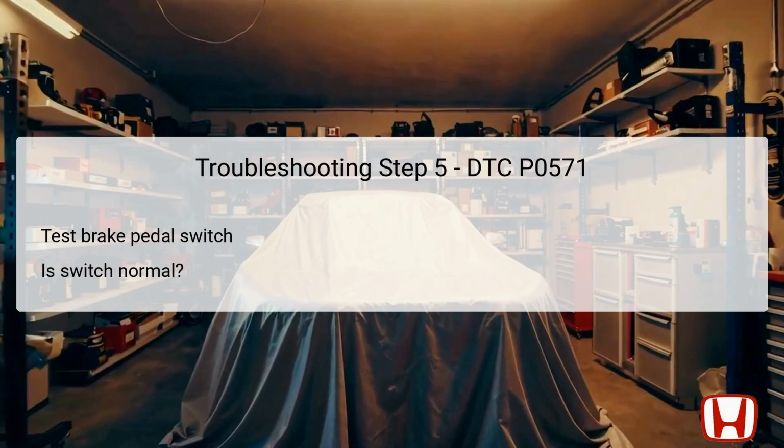Ensuring the switch meets operational specifications allows other diagnostic efforts to refocus on separate wiring or connection issues if the switch checks out fine. In this sixth step, fuse A910A, located in the underhood fuse relay box, will be inspected. This fuse is vital as it provides power to the brake pedal position switch.